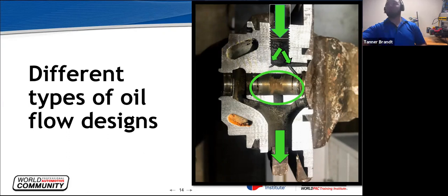So your oil pressure is coming down in through here, but you don't really know how much pressure you're going to have there. Hopefully you're going to have engine oil pressure, but let's say on an old GM, as an example, at idle it might drop down to 10 PSI or something like that. If you had a crankcase pressure problem, you could certainly be higher than that. We would hope you wouldn't be, obviously. Hopefully you're not over a pound in crankcase pressure, but that is a possibility. And if you have pressure here, or this line is clogged, then it can't drain.